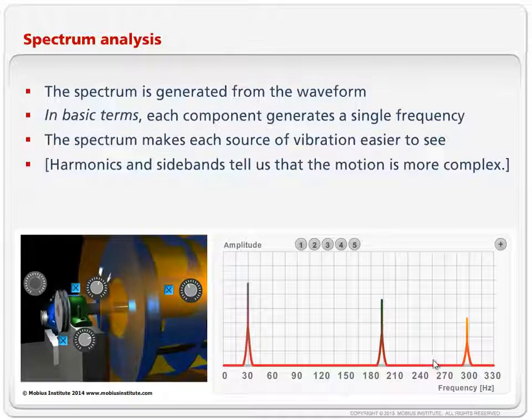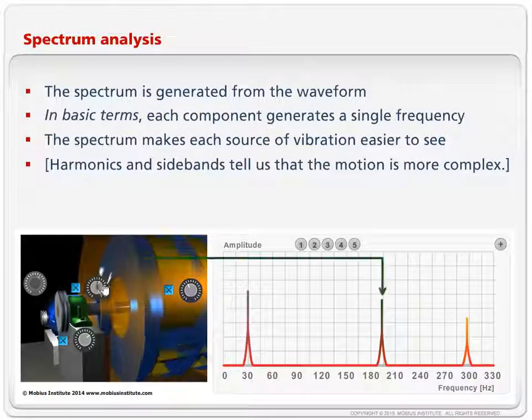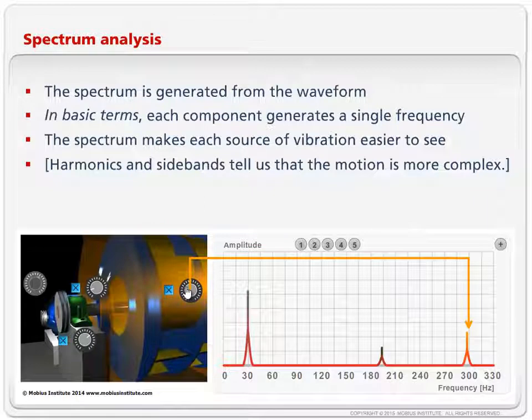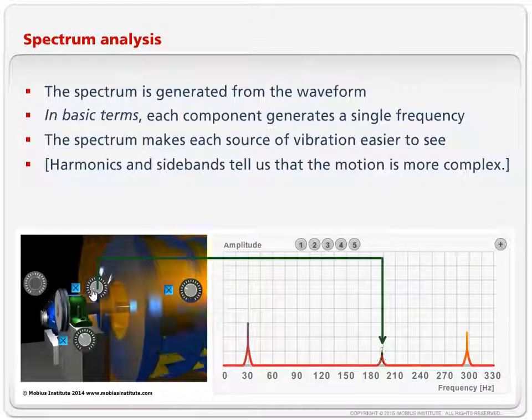If you look, and I didn't line it up very well, but this green vibration is never exactly 9x or 10x or 3x. It's always 3 point something, 5 point something, 7 point something. It always works out that way. But the beauty of all this is that there's the vibration from the shaft, there's the vibration from the bearing, and there's the vibration from the fan. So basically I might take a measurement one day, and it, let's just say, looks like this.